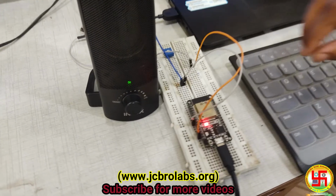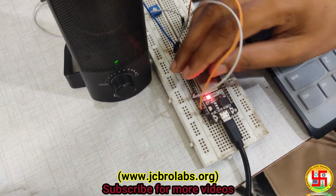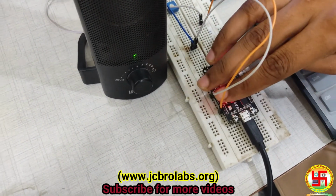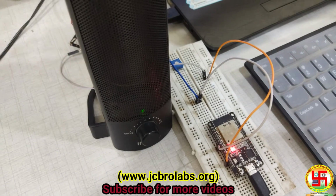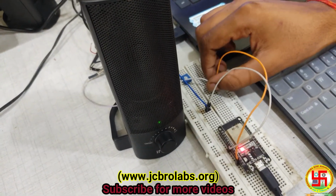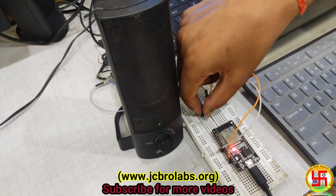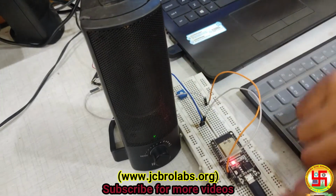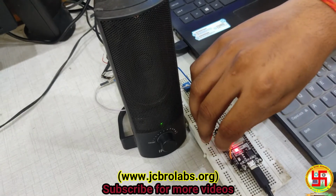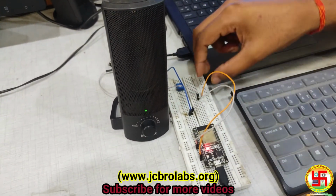You can see here, this is our ESP32, and this digital pin D25 is a DAC pin connected to our speaker pin, and the ground pin is connected to the speaker ground pin. This is our hardware connections.